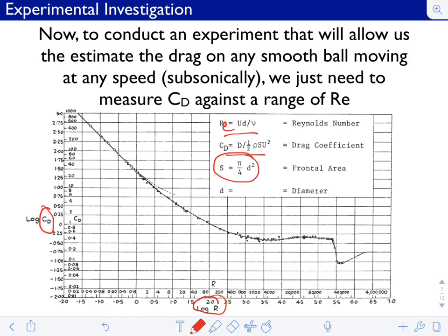And in this particular measurement, you see the flow. As the Reynolds number increases, our CD is dropping, it flattens out, it drops quickly, and then it starts rising again. We'll talk about this a bit more, why it looks like this, when we get into viscous flow. Just in summary, one thing to caution you, and I'll mention this again later, is that just because the drag coefficient is dropping does not mean that the drag is dropping. Let's say you keep everything the same, and we're only increasing Reynolds number via an increase in velocity, so the Reynolds number will be going up. Here it says the drag coefficient's going down, at least for part of this range.